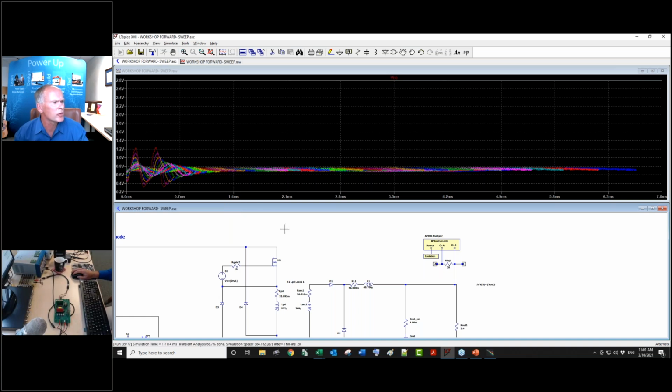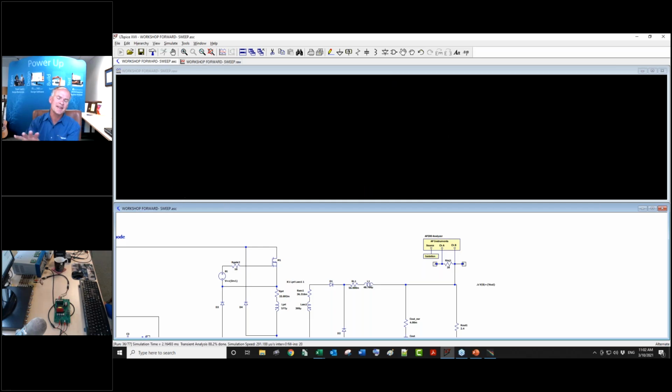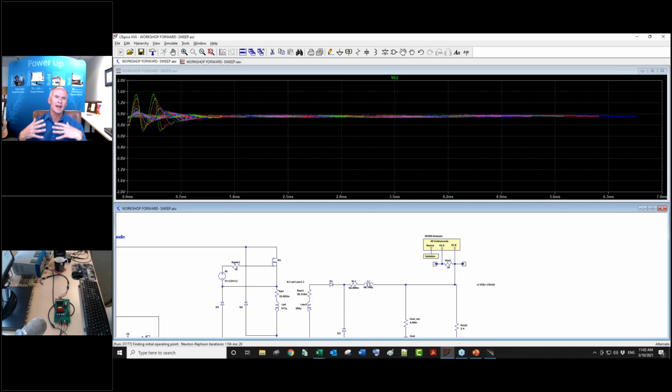Where would the 20 ohm resistor go for constant current regulation? You have to see schematics, always, on these questions. Where do I inject? It gets very detailed. You have to send us your schematic, we look at your schematic, and we say, okay, you need to inject here. Of course, we've got finite bandwidth for looking at everybody's schematics, but everybody's got a unique situation. Sometimes there are 3 or 4 loops in the system, and it's not clear where to look, and you just have to do some engineering thought on what you should do next.